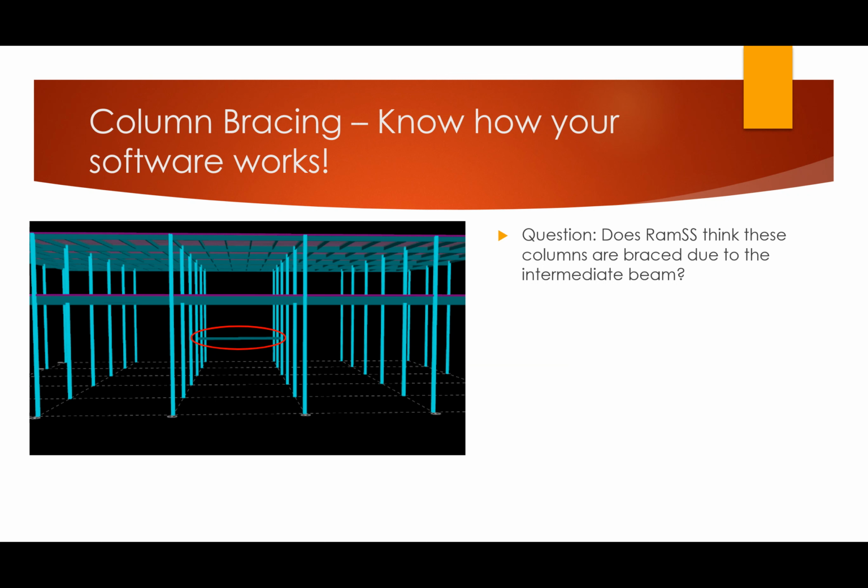This is what really caused me to choose this exact topic here, because our software could easily be tricked into thinking that a column is braced when in reality it is not. Okay, so this is RAMSS, what we use, and apologies to anybody who uses eTabs or any other program. I really don't know if this is a problem or not in other software, but this is definitely an issue in RAM. If you take a simple gravity model like this, these are 40-foot tall columns, and you put an intermediate beam in there, is RAMSS going to think that those two columns are braced at 20 feet?